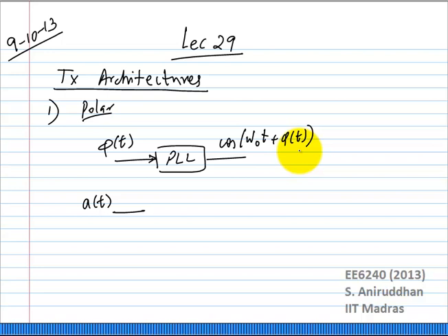How do I multiply two signals? A 4-quadrant multiplier. At what frequency should this multiplier operate? This is an RF multiplier, right? So what kind of circuit would multiply? A mixer is a possibility, but then why even go to all this length of doing the phase modulation through the PLL? As it turns out, there is an easier way to actually combine the two outputs.